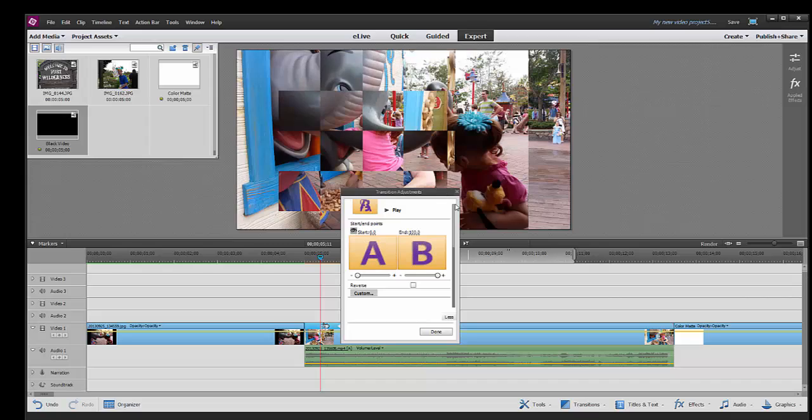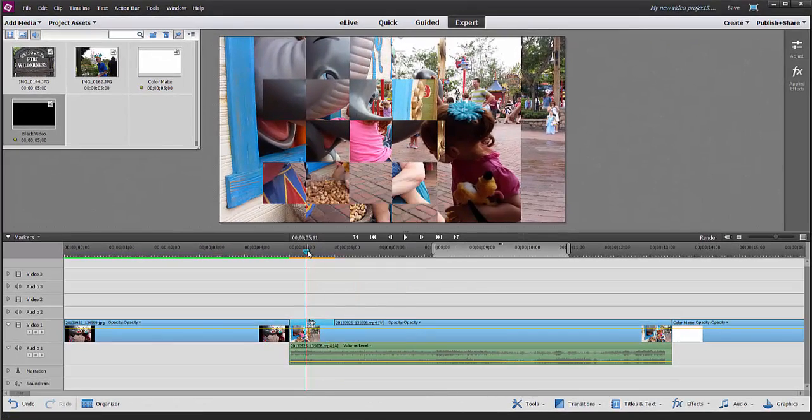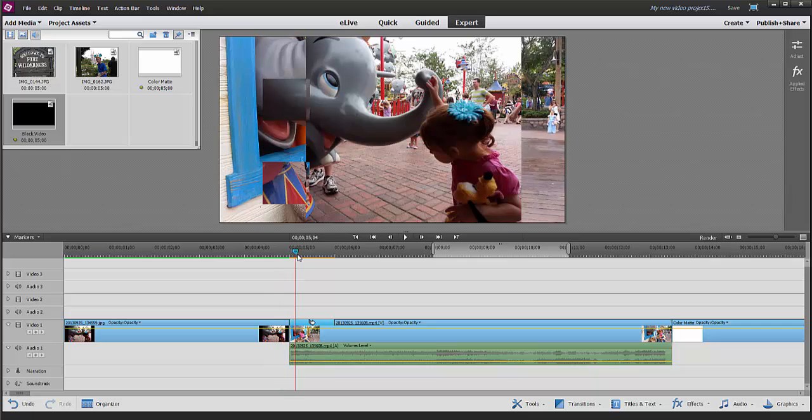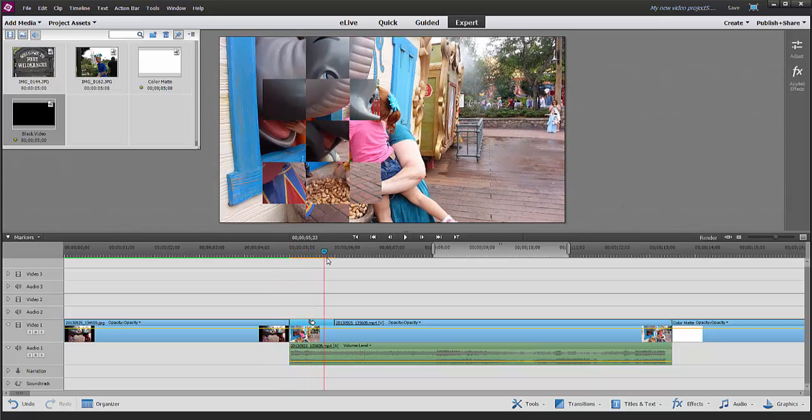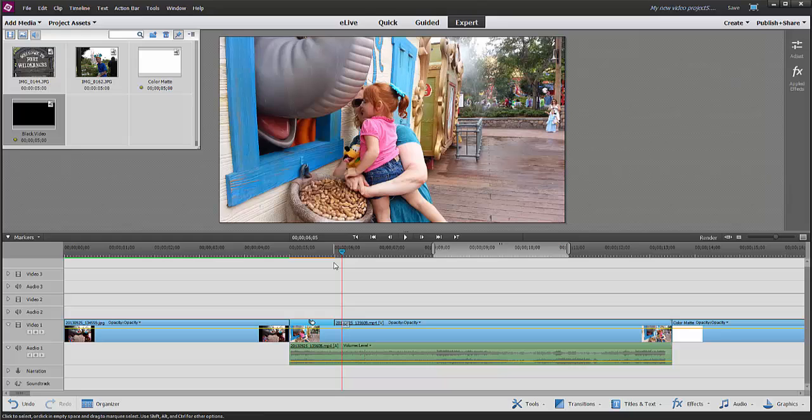Go back again, go to 0, which is the other extreme. Let's see what it looks like now. That's a lot more defined, not as smooth and not as definite and defined sections. So at 0 you get the much more defined gradient areas, so between the gray and the black and the white, versus up on the high end of 127 where it kind of all blends together a little bit more.